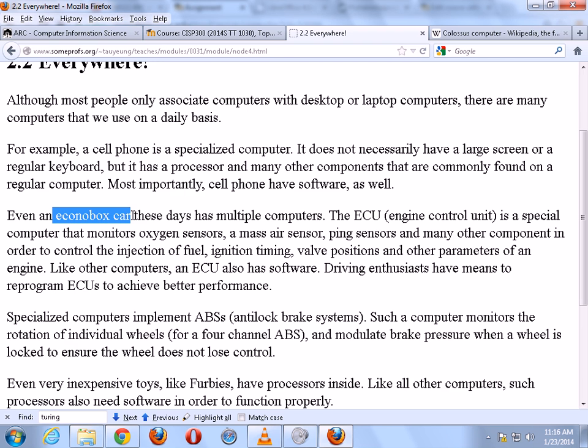It's engine control. Anti-lock brakes has its own computer. Your radio and climate control have their own processor. So when you look at a modern car, I would not be surprised to find 7 to 10 processors easily. The instrument panel has its own computer, and all of these computers are networked inside the car. They have their own networking protocol called CAN, C-A-N, which stands for Controller Area Network.